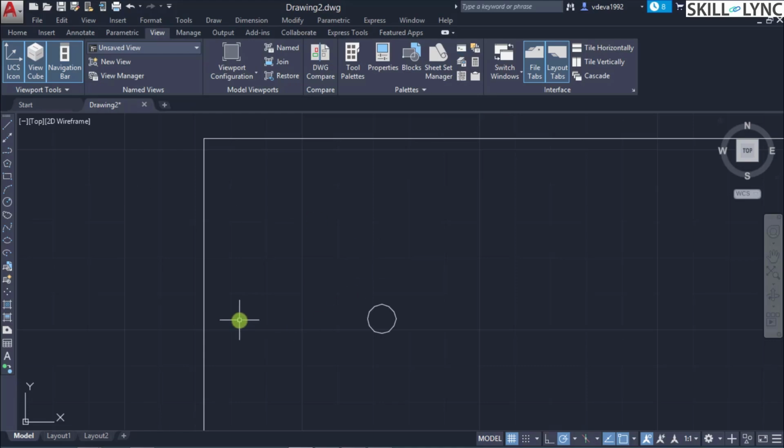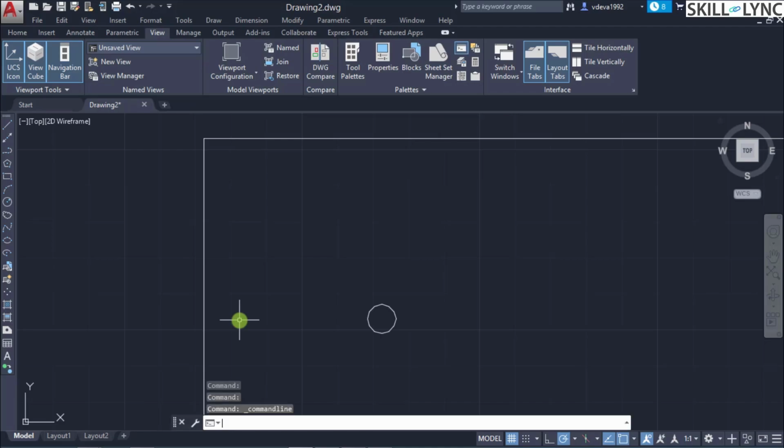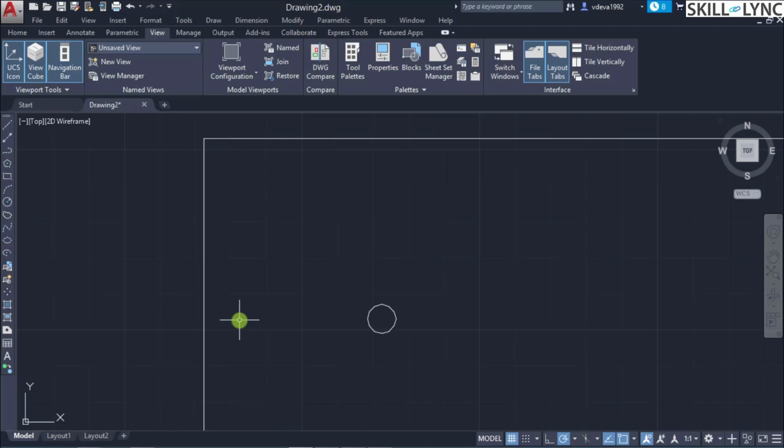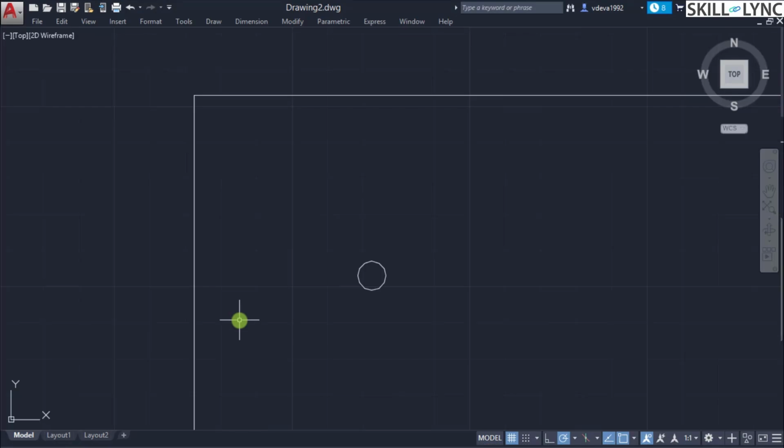That will help you work in the graphical screen itself. Likewise, you can take away the toolbars by using the clean screen command, that is Control plus 0. Control plus 9 works on the command line, while Control plus 0 removes the toolbars and the taskbar to provide more space.